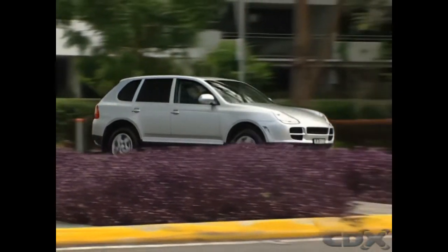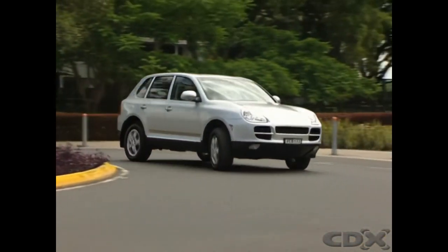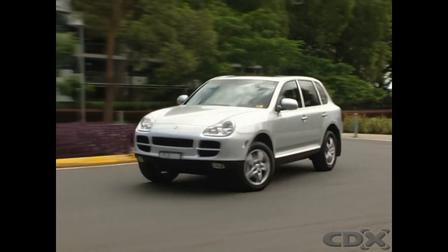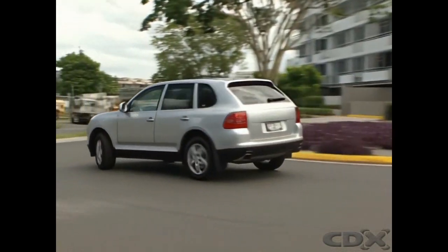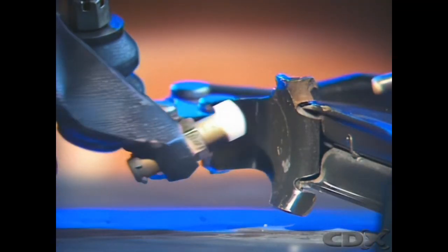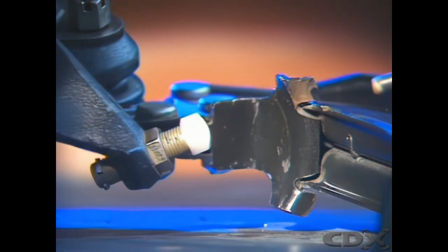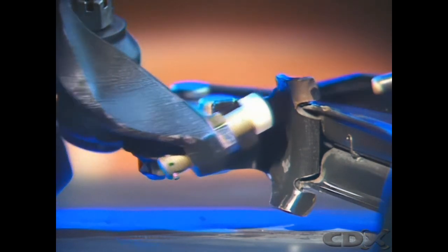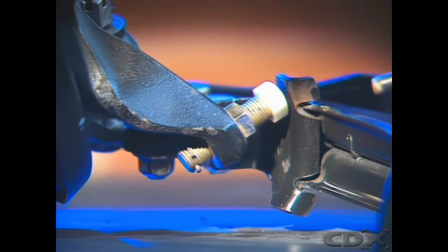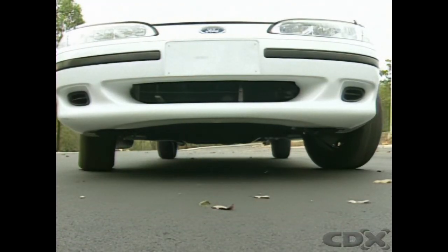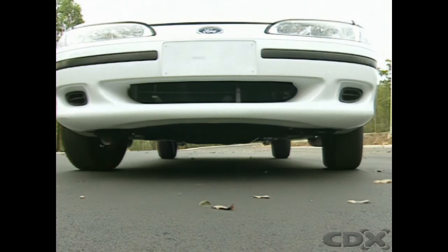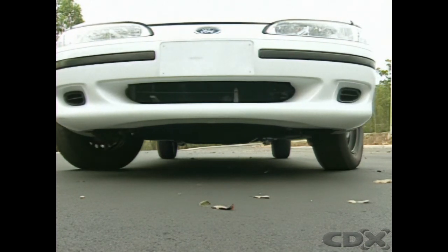Turning radius is a measure of how small a circle the vehicle can turn around in when the steering wheel is turned to the limit. All vehicles have stops to limit how far the front wheels can turn. In some designs, these stops can be adjusted as part of a wheel alignment. If the stops are incorrectly adjusted, they could allow too large a turning angle, and the steering box can be damaged.